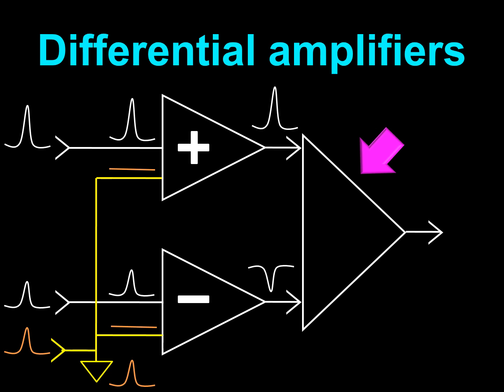In the next step, the differential amplifier will manipulate these values. It will add the values arising from the non-inverter single-ended amplifier to the value produced by the inverter single-ended amplifier. The sum of these numbers will reduce the signal by subtracting all the amplitude that is common to both waves. The process of subtracting all the amplitude that is common to both waves is what we refer to as discrimination.